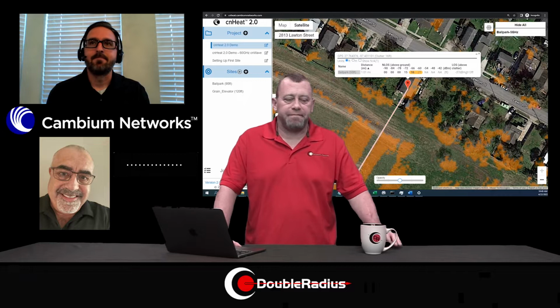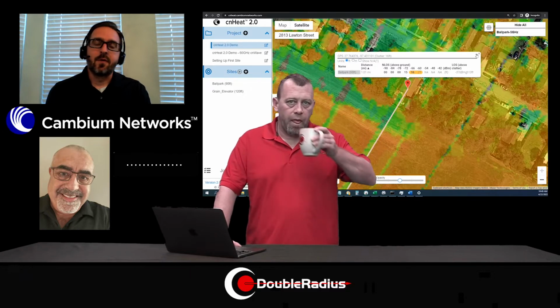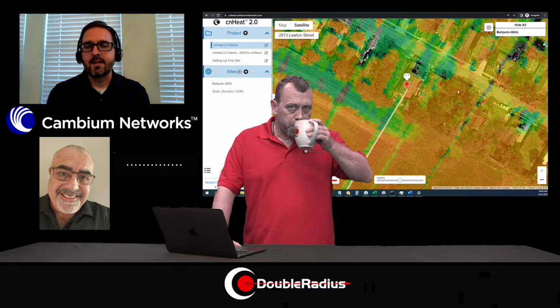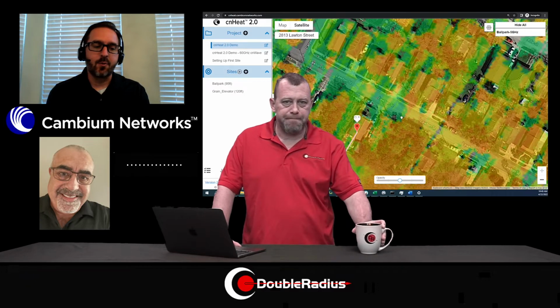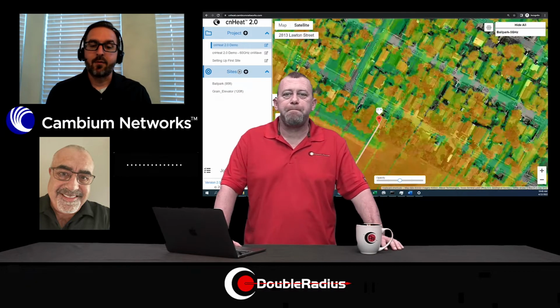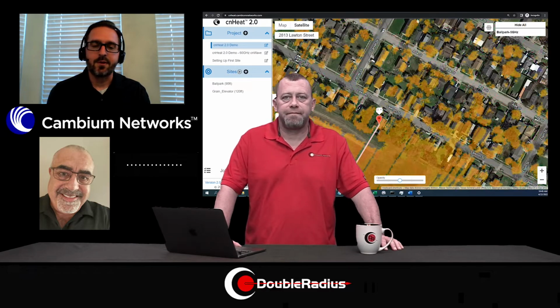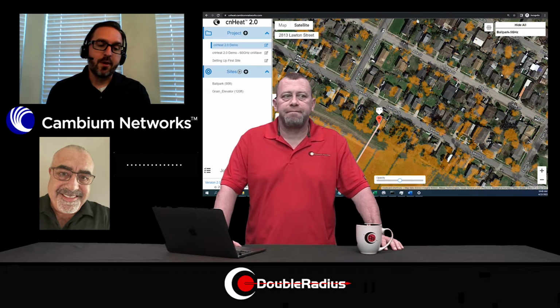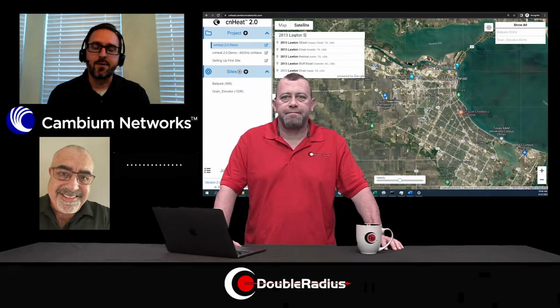It might have just intensity, various things. And we never know what we're going to get. So we convert ours to generalize all of our Lidar so that it's all the same going into the tool. So we down convert to 1 meter, but the underlying data, which shines through a lot, is usually within a few centimeters.